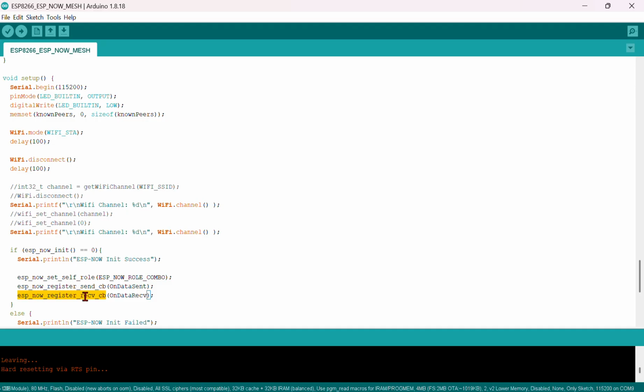In the original source code, the off command will set the logic of the GPIO connected to the onboard LED to 0, and logic 0 will activate the onboard LED. But if we command on, it will set the logic to 1 and it will turn off the onboard LED.